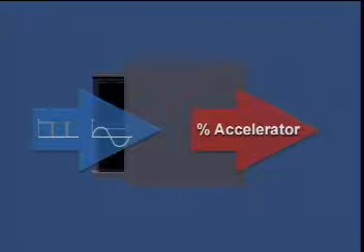The frequency throttle feature converts a filtered throttle frequency input into a requested throttle percentage. This feature applies to industrial and marine applications where a position or logic signal is not appropriate. The remote throttle can also be used in addition to a frequency throttle.